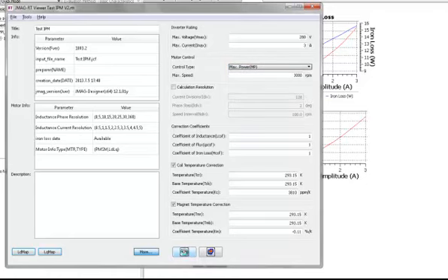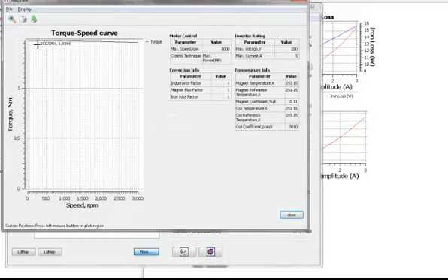So the speed torque curve is just going to draw on the same data, and instead of mapping out the efficiency at every operating point, all we're going to do is look for that envelope of speed versus torque. So it's effectively the same mapping function that we saw before without generating the efficiency maps in between. We'll wait a couple seconds here and look at that speed torque curve, and you can see again it's effectively just the same outside envelope or operating envelope that we saw with our efficiency map.